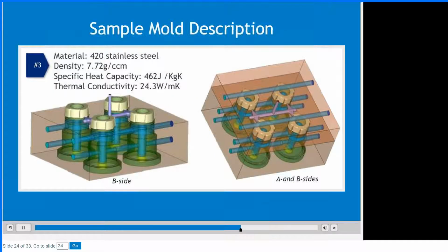In this next example, the movable mold half-core insert and waterline setup have been modified. The center core is now comprised of the entire movable half-core. The ring water circuit is moved closer to the parting line, and an additional baffle circuit is added to the center core section.